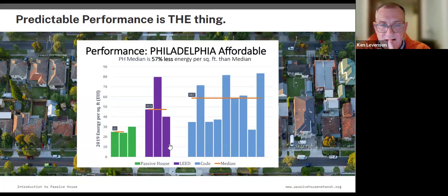And the typical buildings down the street had 12 to 15 tons of air conditioning on them, which would be very typical for that type of house. We calculated that we needed 1.5 tons for the building, which is the equivalent of a window AC unit for your living room, and we're doing a whole 5-story house with it.